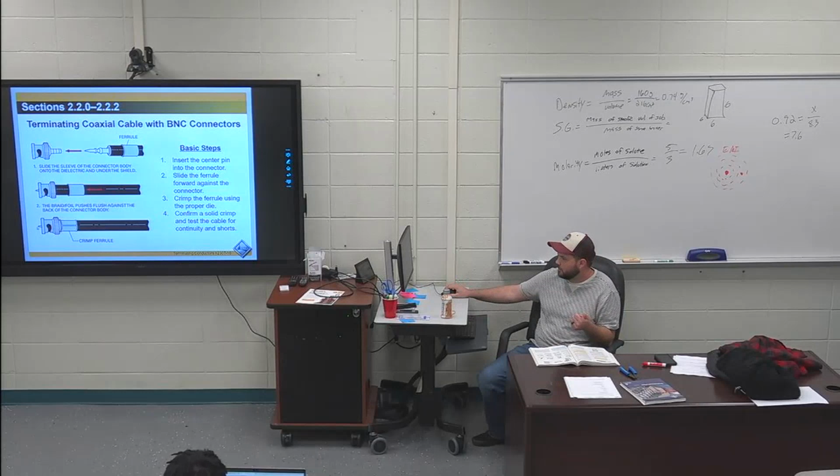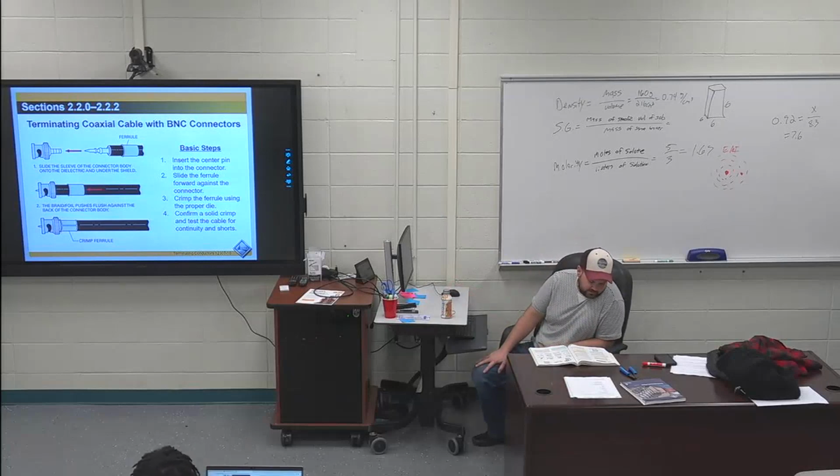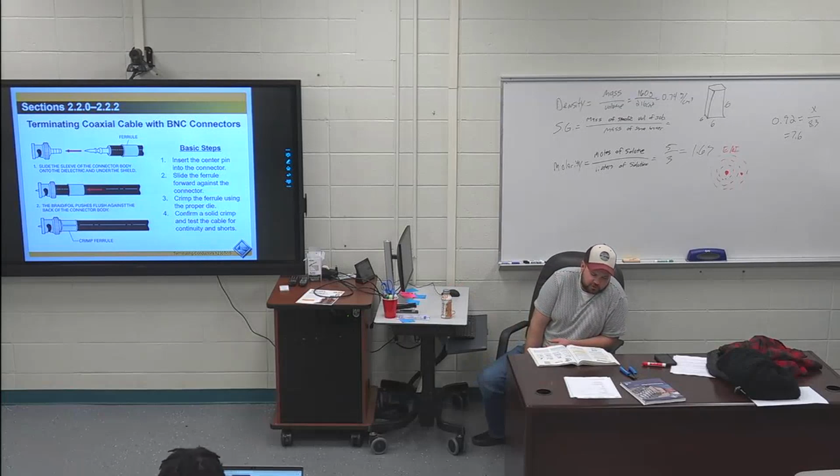And then I put it on the center pin on this side, center pin on the other side, and make sure there's a connection. And then I put it on the center pin and the outer side on this side and make sure there's no connection. Does that make sense? So that's step 18 on page 32 that is highlighted.